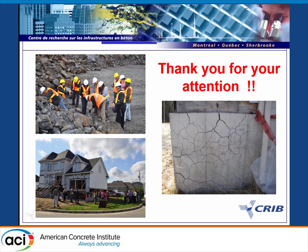Chalcopyrite is a copper, iron, and sulfide. There are a lot of different minerals containing sulfide and iron, and it's difficult to quantify. It's like saying, can you just measure the silica content of your aggregate to know if it will be alkali-silica reactive or not? I think there are too many sources of silica in an aggregate particle to be able to detect ASR according to the SiO2 content. I think it's about the same thing here, because you have a lot of aggregate particles with sulfide, pyrite, or pyrrhotite and other sulfide minerals. Okay, thank you.